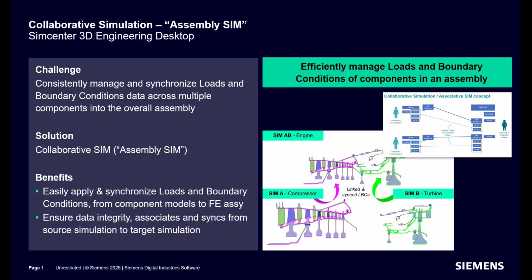Analysis models represent systems that can be constructed from components. SimCenter 3D supports this concept through Assembly FEM. A benefit of Assembly FEM is that multiple users or batch processes can construct component meshes which are later brought together in an assembly. But what if your components contain loads and boundary conditions?